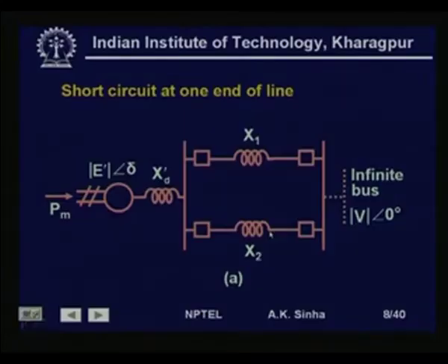That is, most of the time the faults which occur on the power system are transient in nature. That is, once you clear them, if you again close the line, things will become normal. So a fault has occurred, and if we clear the fault and after that reclose the circuit after a short time, then the circuit will in general be normal.